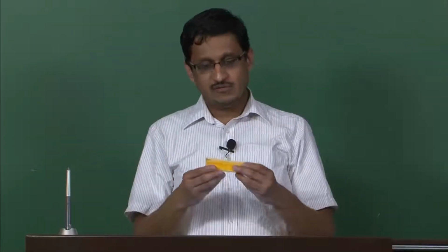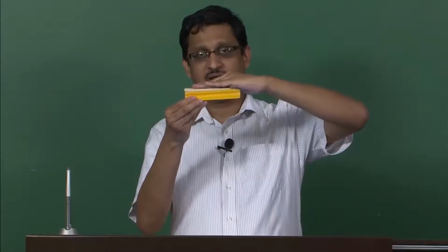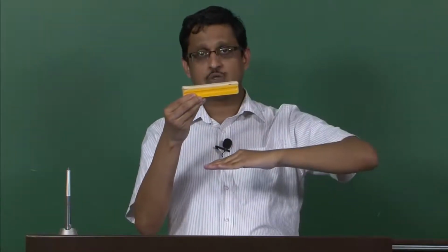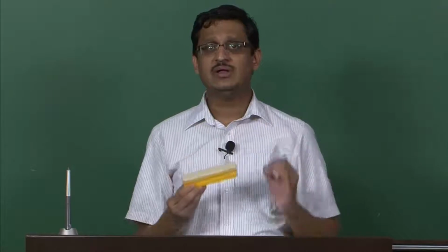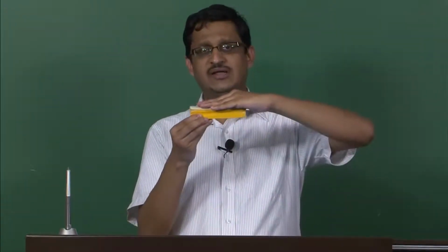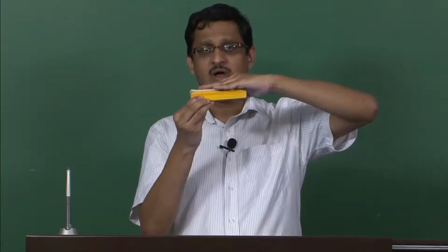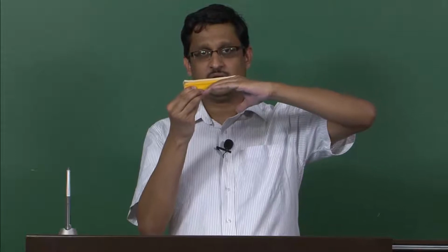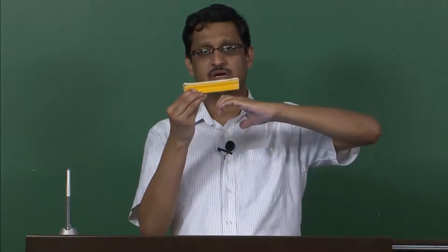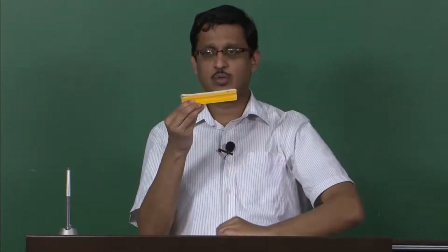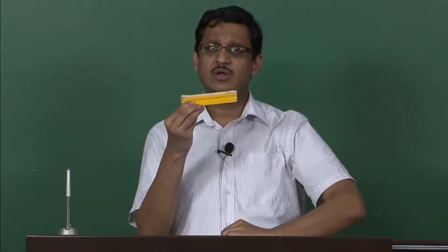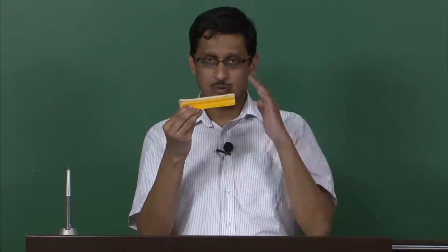So, if this is the variation of the electric field inside the material, so should be the variation of the current density J. On the surface you have the current density J0, which is given by sigma times E0, and the amplitude of the J vector starts to reduce, eventually going towards 0 at Z equal to infinity. Okay. This was all about electric field.